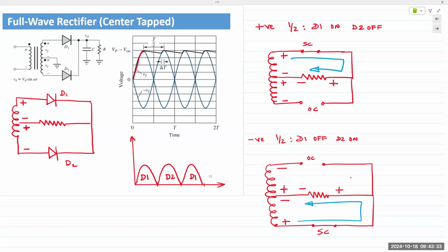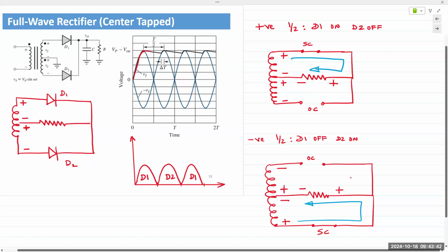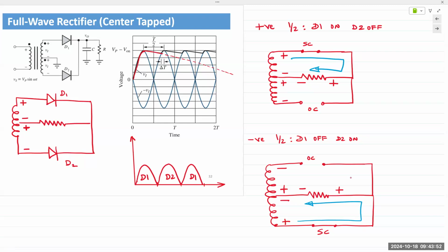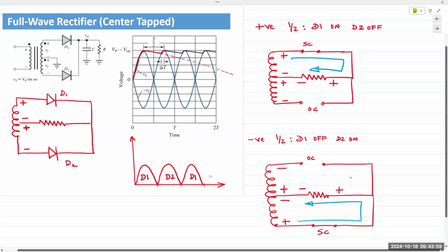So the capacitor is large enough, it'll start discharging when the cycle goes negative. But when it begins discharging here, if you let it go, it'll discharge at some point in the future. But before it can discharge anywhere below like 90%, the next positive half cycle arrives, and instead of discharging, it starts charging again.